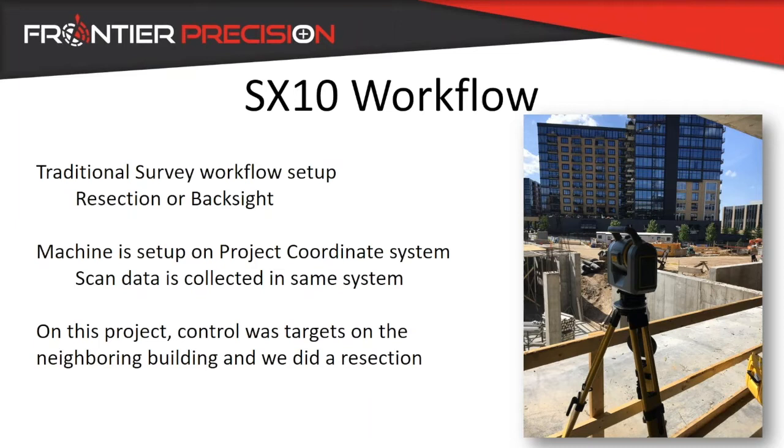You get your residual results, it's all right there for you. When your machine is set up, as I just said, you have your scan data. It's right there in the exact same coordinate system, whether it is an assumed coordinate system of say 5,000, 3,000 for the building, or you're on, as we were, county coordinates. Whatever it is, your scan data is right there with you.